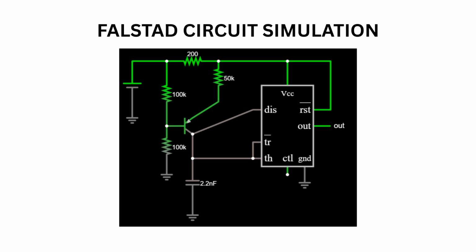The resistor values are chosen such that the capacitor discharges slowly, producing a nearly linear negative ramp, and then resets quickly, resulting in a sharp vertical rise. This behavior closely matches the reverse sawtooth waveform analyzed using Fourier series.